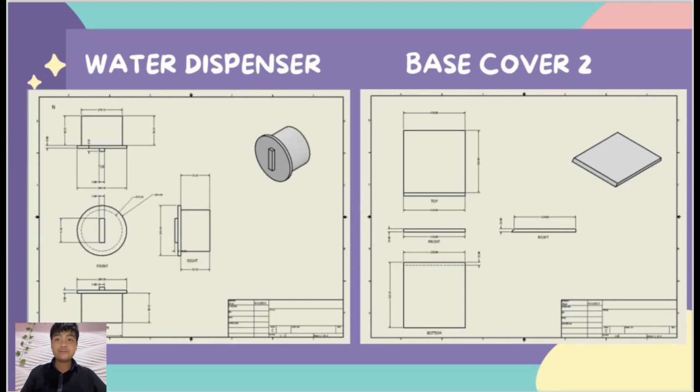As for the front view, the first diameter is equal to 70 millimeters of diameter, and the second circle is equal to 84.89 millimeters of diameter, and the measurement for the handle is equal to 9 millimeters, and the height is equal to 41.01 millimeters.